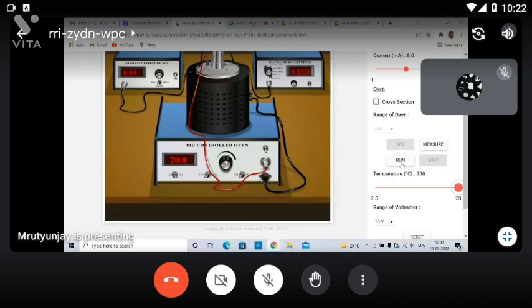One is written as run. After clicking run one, the temperature will start increasing and the corresponding voltage will also change. Right now I'm going to note down the first observation at 30 degrees Celsius. Just click run one. It has changed in multiples of 10, so just wait up to 30. When it is showing 30, you need to click the wait button. Done for 30 degrees Celsius. This is the voltage in millivolts. Clear or not clear? Yes, sir, clear.